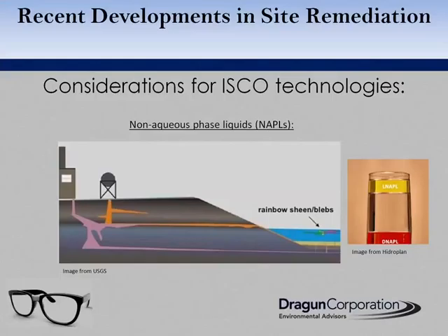The quick cliff notes for NAPL mobility, since there's a lot of science out on this now, is that a NAPL dissolves gradually into the saturated zone until a quasi-equilibrium is reached between the layer of free product and the aquifer. Also, once a source is removed, NAPL requires other processes to help it move or degrade.